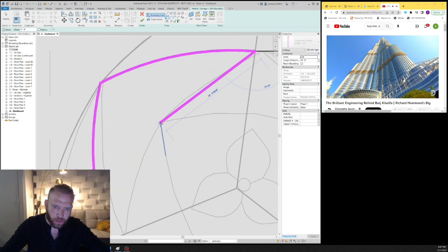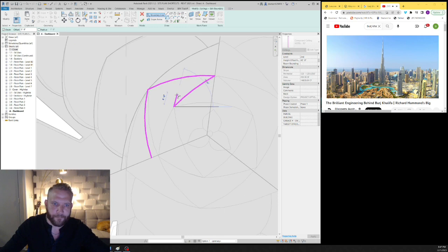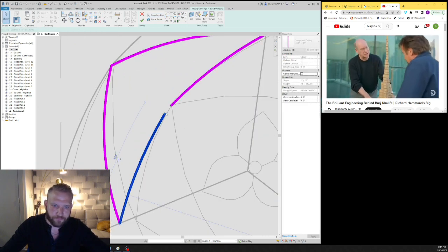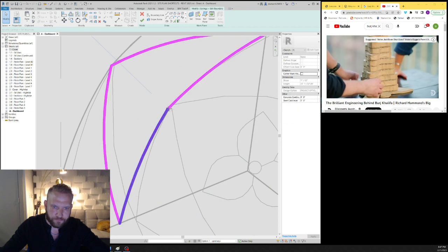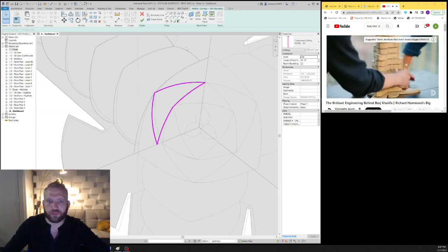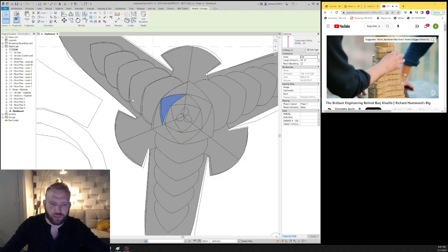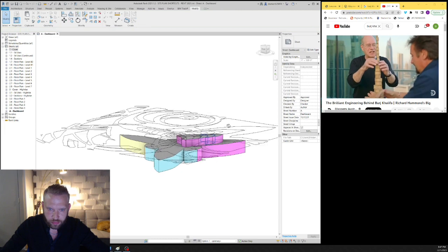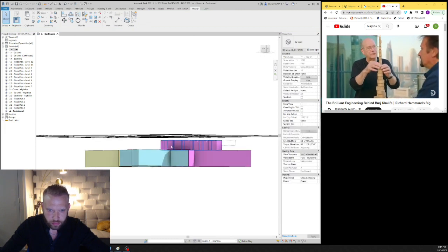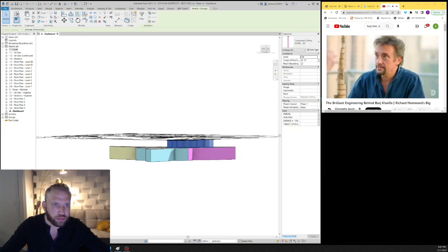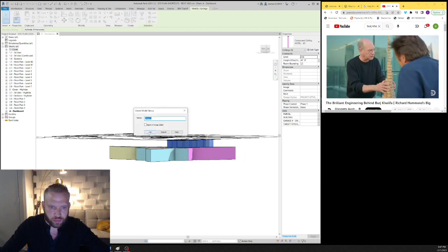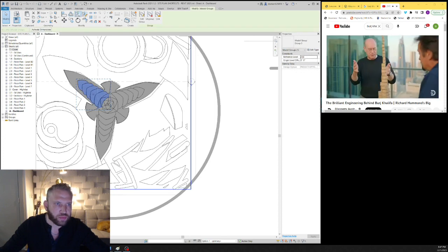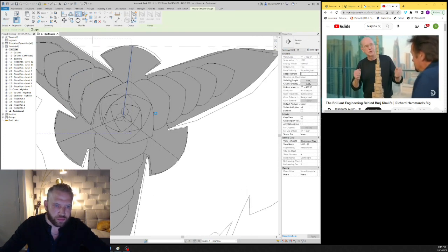To stop that happening, Bill and his colleagues had to design a skyscraper radically different from any other. This is essentially the Burj Khalifa. The key aspects of this is how the shape of the floor plate constantly changes. As we go up, there's 27 different shapes in the tower, and each of them will generate vortices slightly different than the ones above or below them. So you never get really large forces on the building because they're always coming off at different rates. And because of that, the wind never gets organized. We actually call this confusing the wind.